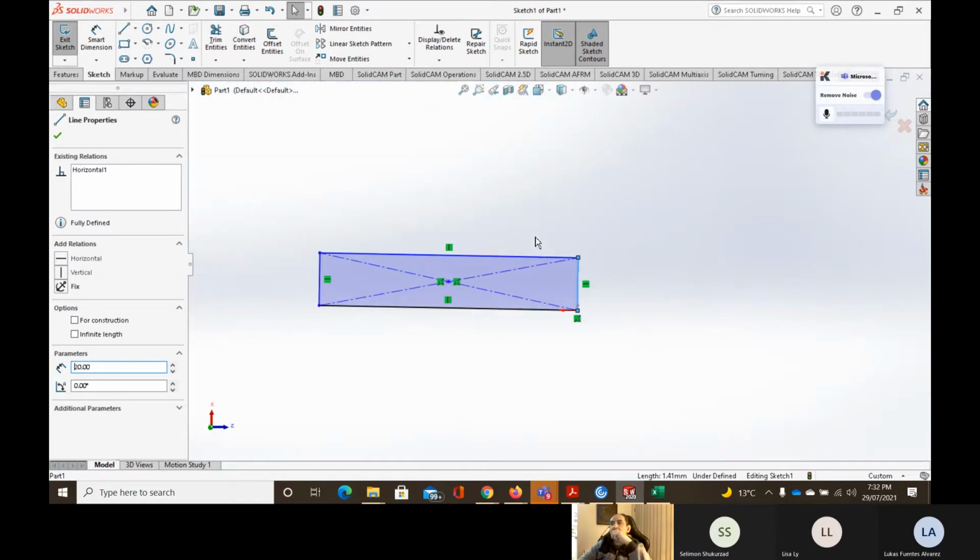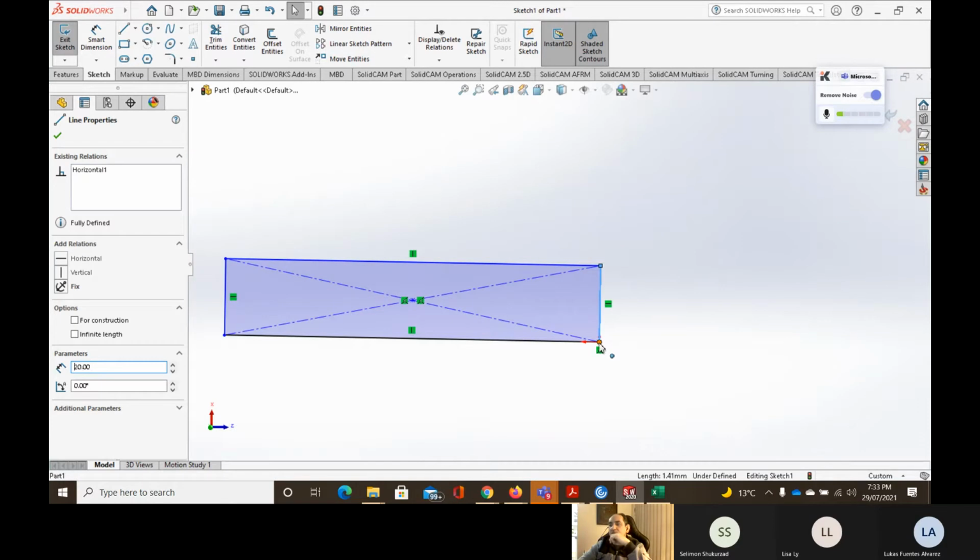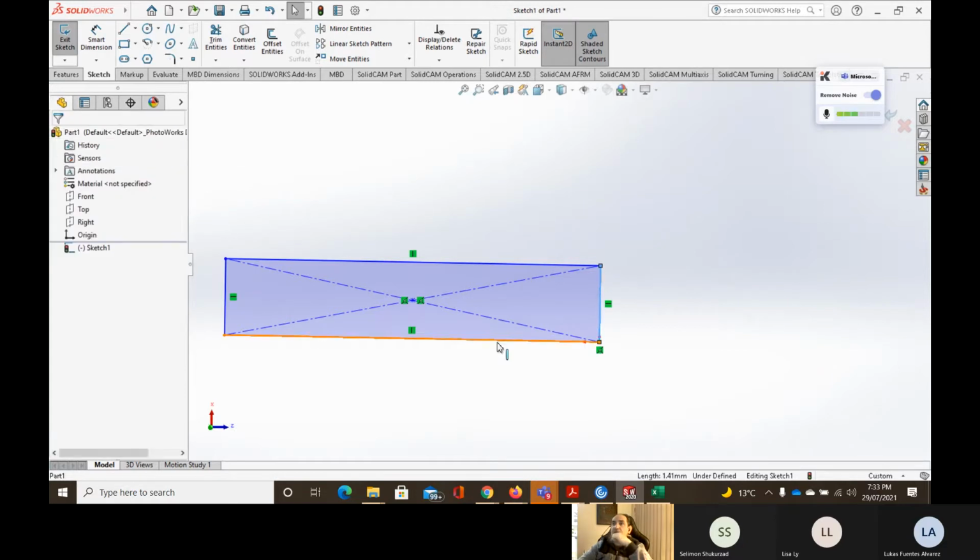Okay. That point is going to be the datum point. So everything behind is going to be zero, negative, sorry. Everything on the right is going to be positive, and this will be the x value. The x value, we're always going to deal with diameters, not radiuses, unless we're going to set up the machine to do something else. Now, just to remind you that this meant to be a cylindrical shape.